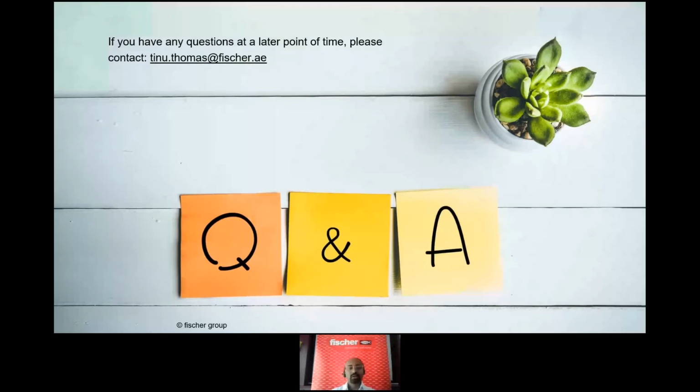So if you have a third loading direction, you should preferably use a serrated channel or a notched T-bolt. I hope, Mustafa, I was able to answer your question.